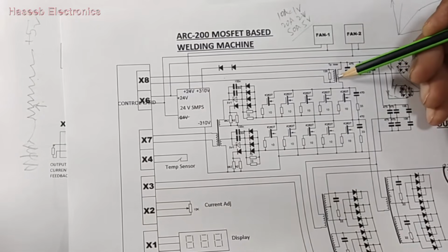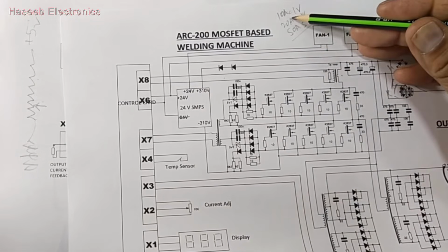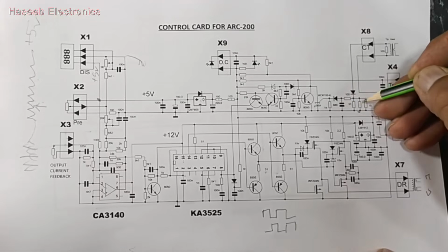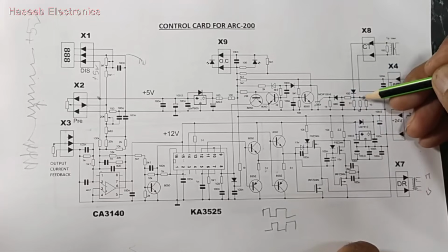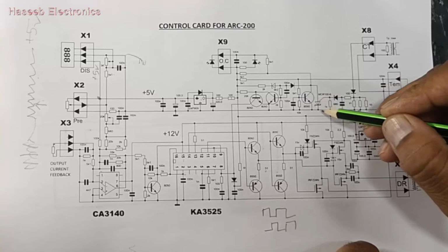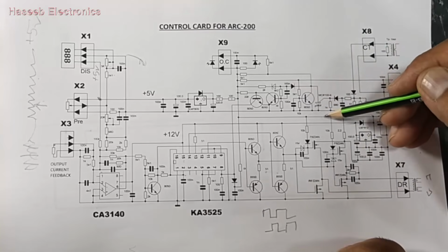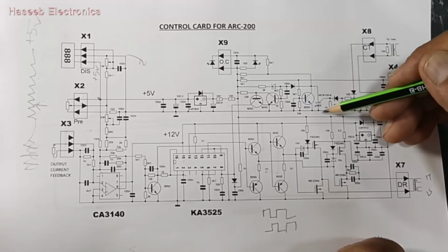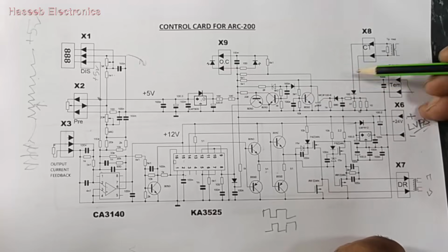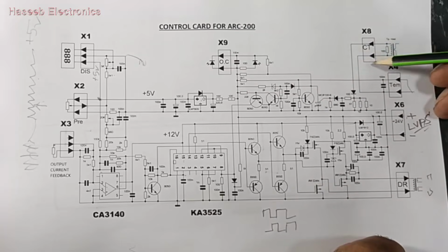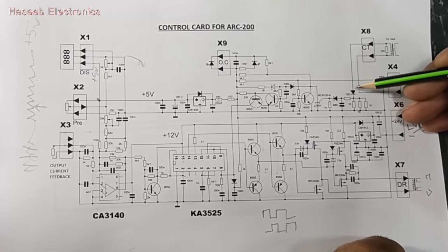As I was discussing here, for the current sense current transformer circuit at this resistor network, this configuration, here we have MCR 100, that is SCR. SCR has terminal 1, terminal 2 and gate trigger. We apply some feedback signal, some sense voltage that is reaching here.